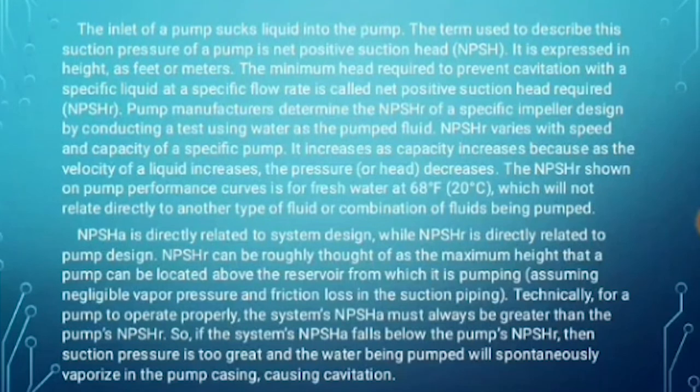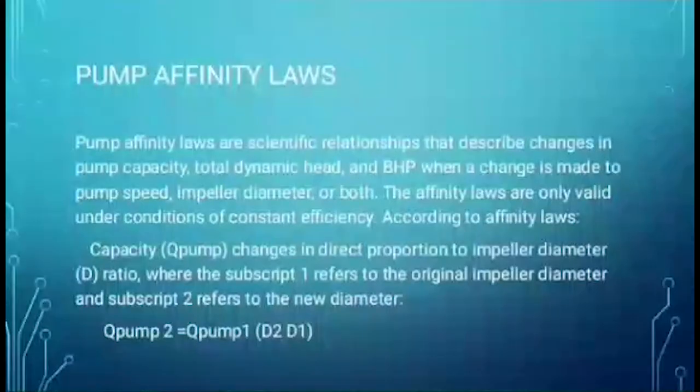NPSHA is directly related to system design, while NPSHR is directly related to pump design. Technically, NPSHA must be greater than the pump NPSHR in order for the pump to operate properly. Otherwise, suction pressure is too low and the water being pumped will spontaneously vaporize in the pump casing, causing cavitation.